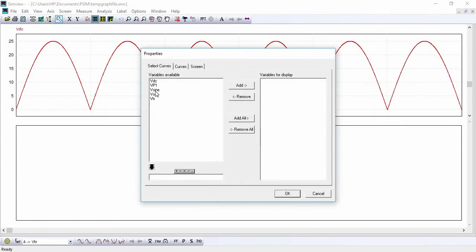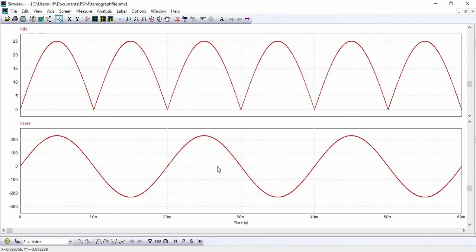Here we'll have our input signal. Our input signal is like this. So our rectifier will work. Our AC signal will be converted into the DC signal. Here we can see that in the first cycle we are getting a positive cycle, so it is as it is in our DC waveform. While for the second cycle, our diodes D2 and D4 will try to convert this negative cycle to a positive one.